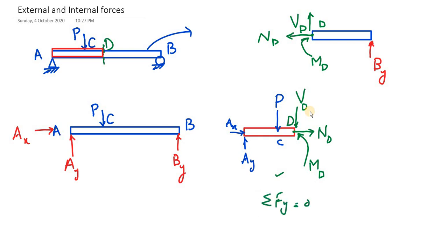Whenever I apply an equilibrium condition, I must set up a local sign convention for that equilibrium condition. Local sign convention means that it is just for this equilibrium condition. I have decided that I will treat upward forces as positive, and downward forces as negative.